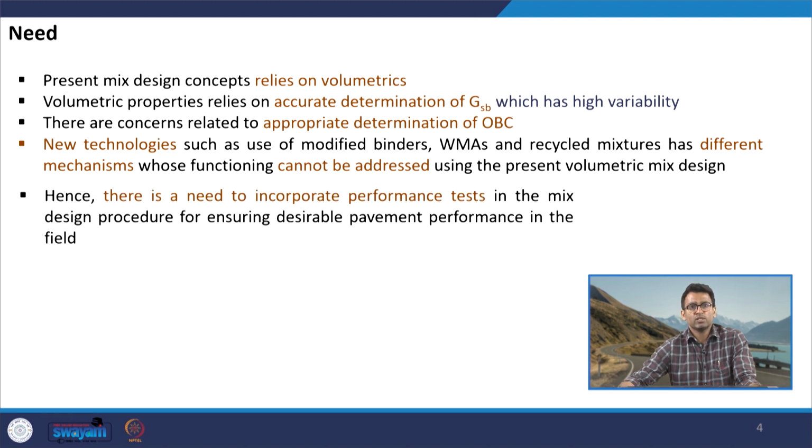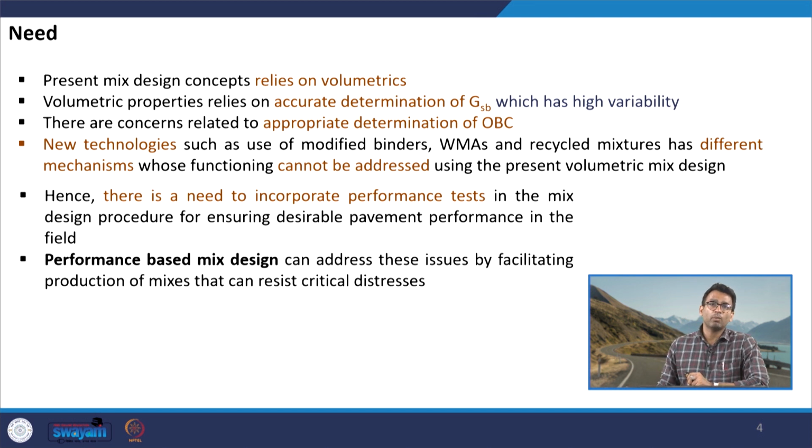Therefore, there is a need to incorporate performance tests in the mix design procedure, to ensure that once we produce the mix in the laboratory, this mix is going to give us desirable pavement performance in the field. When I say performance test, I am basically indicating the various distresses which are going to occur, and the tests which are carried out in the laboratory to see the sensitivity of the mix to these particular distresses.